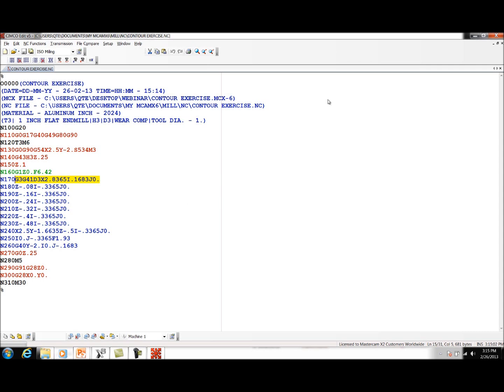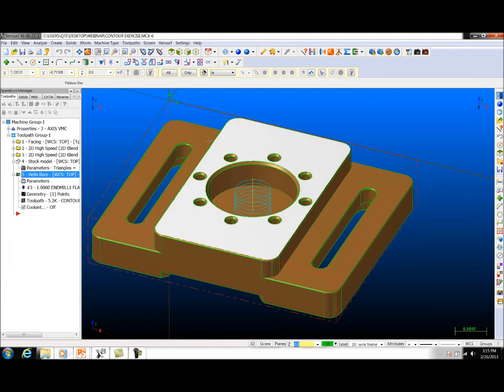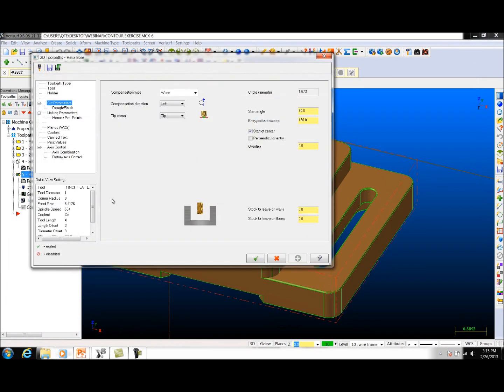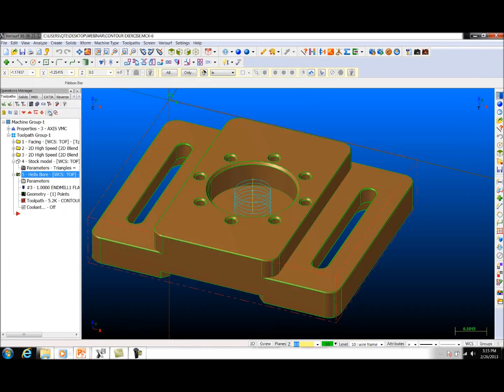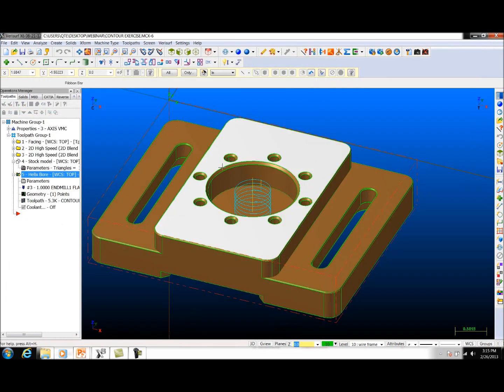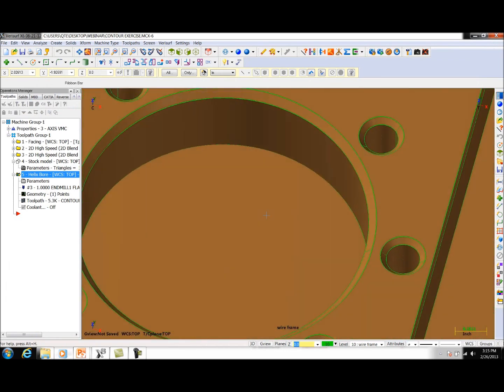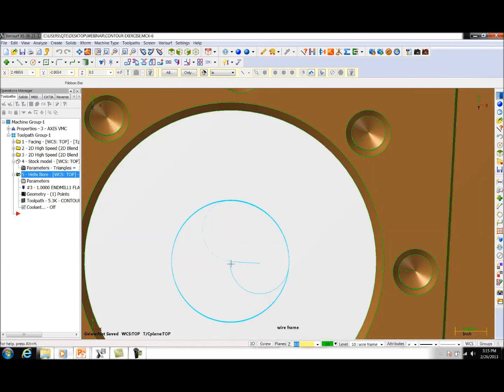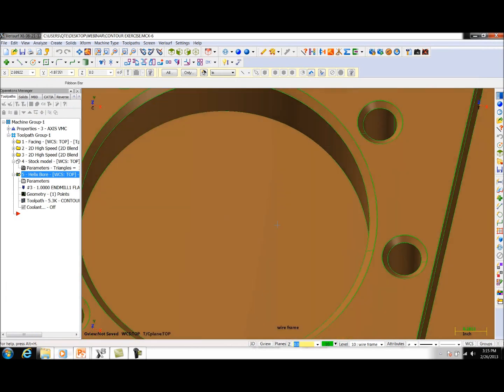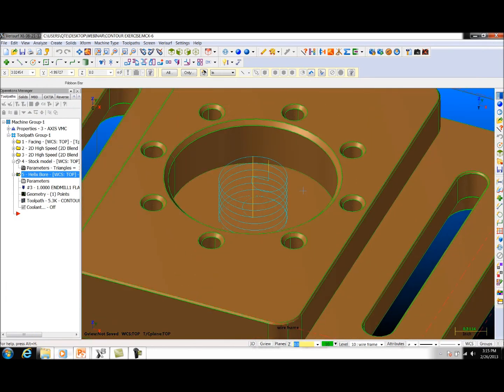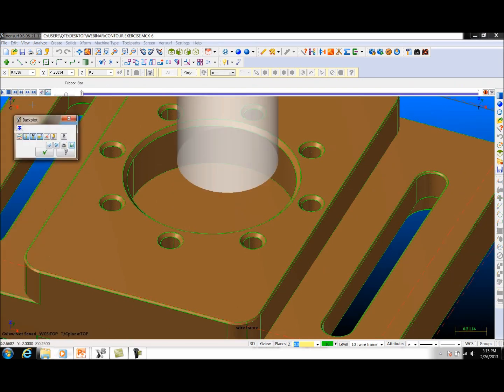Now to alleviate this, we go back into our parameters and we do a perpendicular entry. By perpendicular entry, it adds that little line right there that picks up the cutter comp now. Okay. So now I wrap it off center, pick cutter comp up, now do my arc.